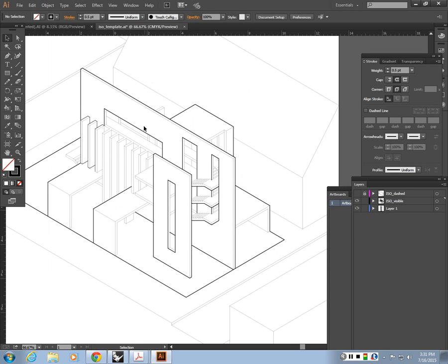So you just have to do this to a few main components of your design. Trust me, you don't want to just add 2 everywhere. That's why I only added it here. I'm highlighting this guy, this guy, these 2 and this one, and the rest I'm just going to make them lighter. So that's how I go from out to in when I'm doing axonometric line weights.